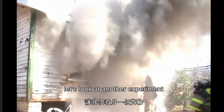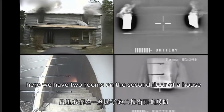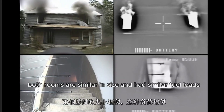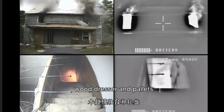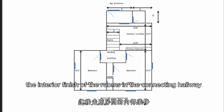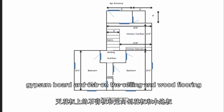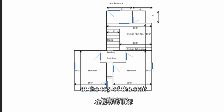Let's look at another experiment. Here we have two rooms on the second floor of a house. Both rooms are similar in size and had similar fuel loads, consisting of a wood bed frame, mattress, box spring, wood dresser, and pallets. The interior finish of the rooms in the connecting hallway at the top of the stairs consisted of wood paneling and oriented strand board on the walls, gypsum board and OSB on the ceiling, and wood flooring. The open doorways from each bedroom are opposite each other at the top of the stair.